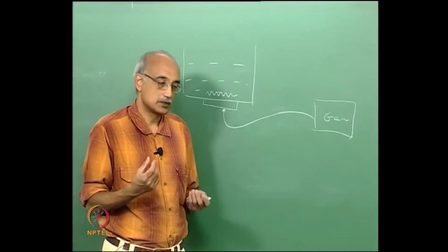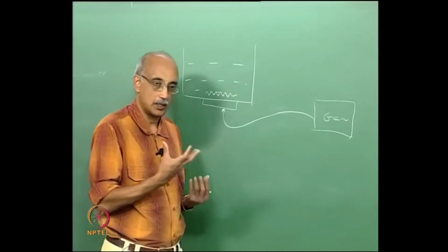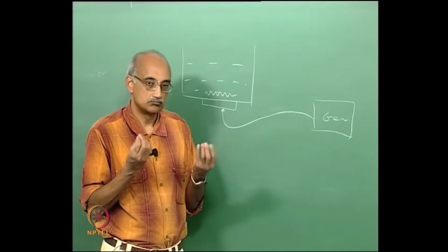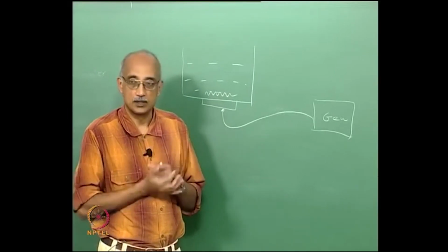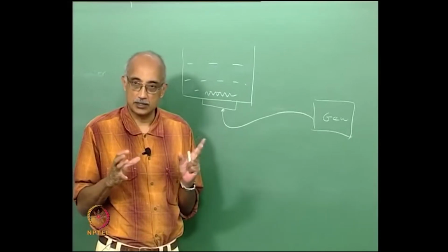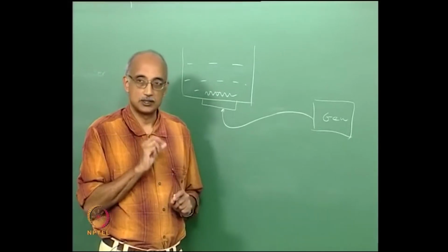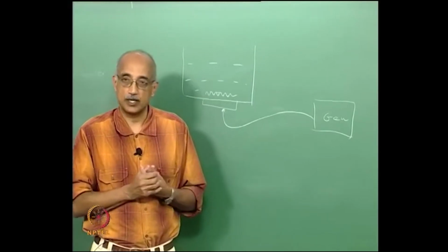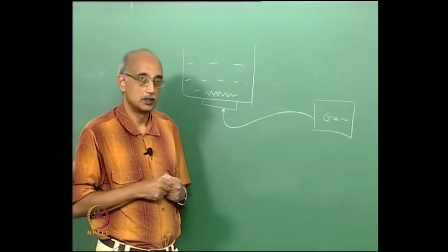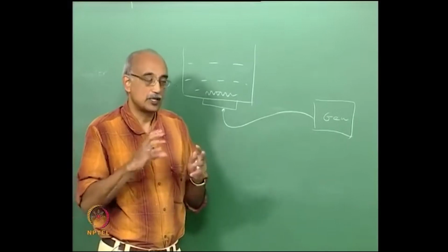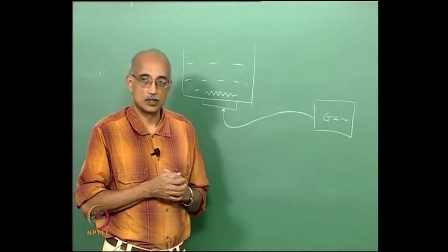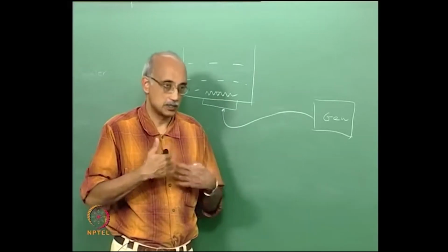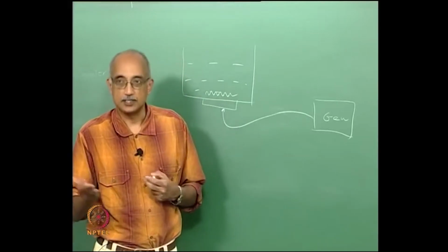Now what happens when you take a liquid and you expand it? It breaks into bubbles. So during the expansion phase, you start forming these bubbles in the liquid. The next phase is compression. During the compression phase, you are squeezing the bubble, and ultimately it implodes, it collapses on itself, and as it does, it releases energy as a wave.